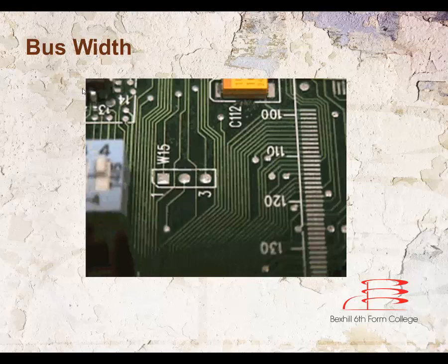In fact, you can run a 64-bit processor on a 32-bit bus line. What does that mean? Well, for every execution the processor could undertake, your bus has to carry the data twice. So if it's got 64 bits in its memory that need to go to the processor, it will send 32 bits and then send another 32 bits. They normally will be similar nowadays, but there's no reason why they have to be the same. They are always a multiple of one or the other.